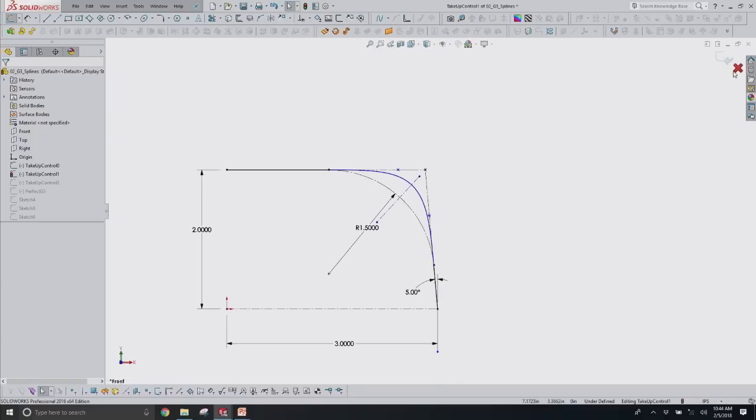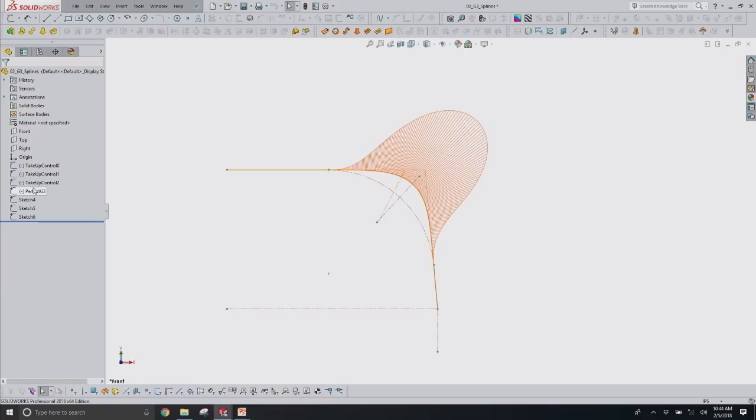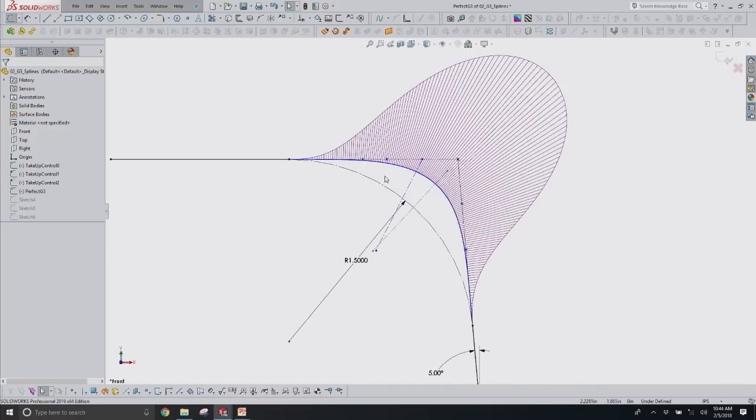What if we go 1 step further? So we're going to go perfect G3. Let's take a look at this sketch. Here I was able to create a perfect G3 connection. The way I did this was creating 3 line segments in each portion of the curve.